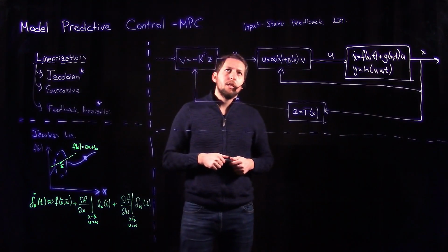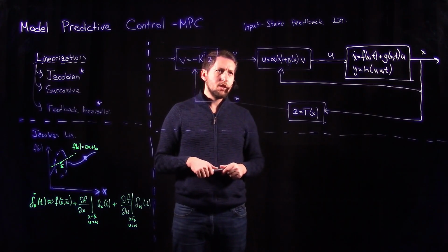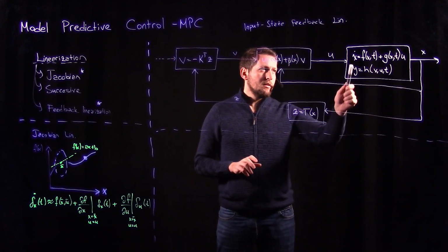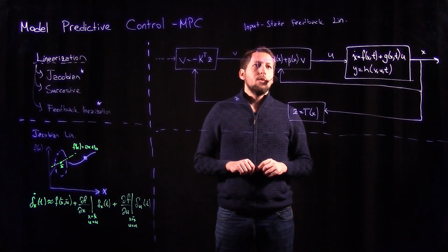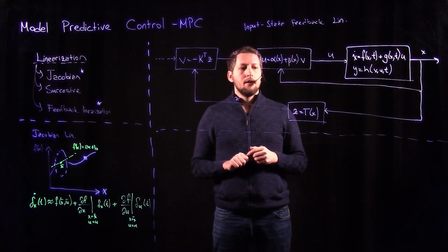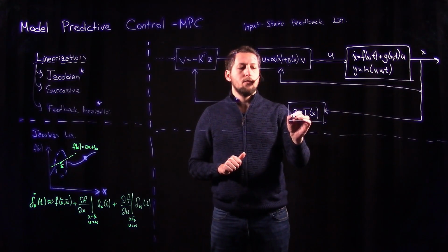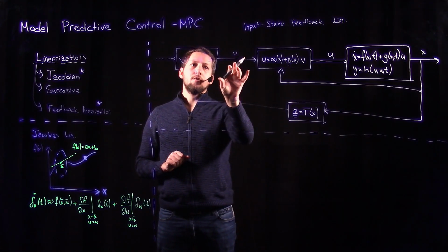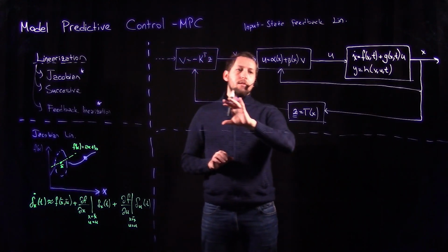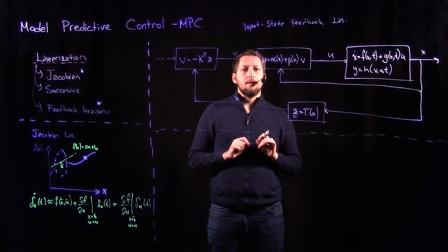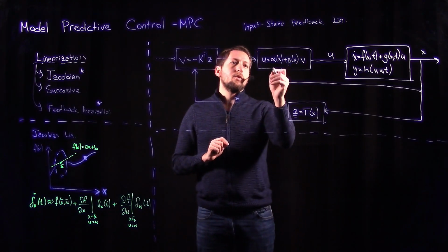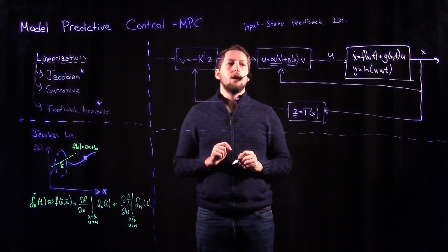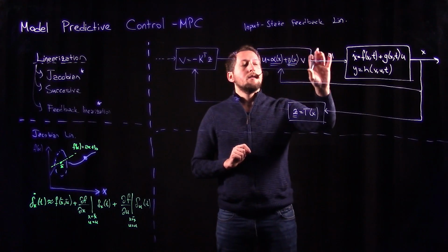Another thing that you can do in terms of linearization is the feedback linearization, and as I have previously mentioned, there are two main options. The first one is the input to state feedback linearization, and I have tried to sketch the main diagram of it here. So basically we have our system structure here, which is nonlinear, as you can see from the representation. And what we are aiming to find is a map of the states to an additional variable z, and using this z and the feedback control structure, we are getting an artificial variable v, and at the end of the day, our system from v to x seems like a linear system. And in order to do that, of course, we need to determine this alpha(x) and the beta(x) and use this new artificial variable v here, and then only this generates the compensated input here.